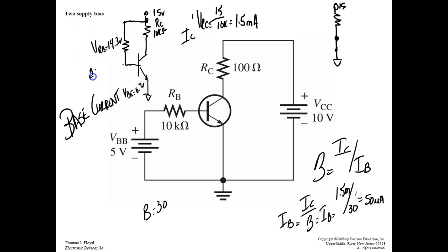Now, why did we go down? We would always round down. Why would we round down? Because this is the exact size resistor to cause it to saturate. If we put more current in, you can't saturate it more than saturation, right? You understand? So we'd always round this down, and then we check the tolerance, but we'll talk about that later.